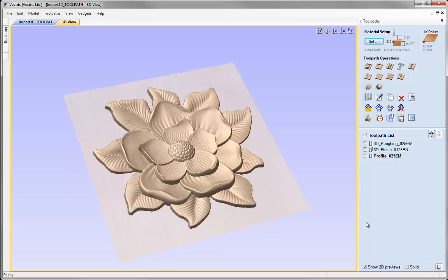and so you can see the file as we've set it up here in the project folder. So there we've seen the process for importing a 3D object into the software, orienting and positioning that object, setting its height, and then coming over to the Toolpaths tab in order to do our material setup, 3D roughing to hog out the majority of the material, the 3D finishing cut to get down to the main surface of the part, and then finally creating a vector so that we could do a profile cutout.